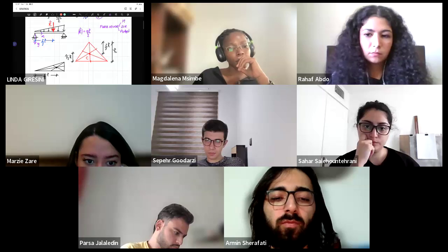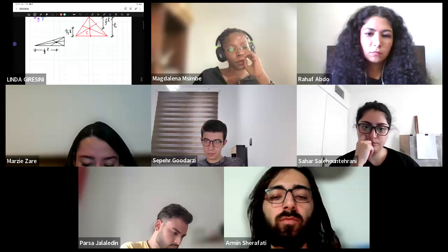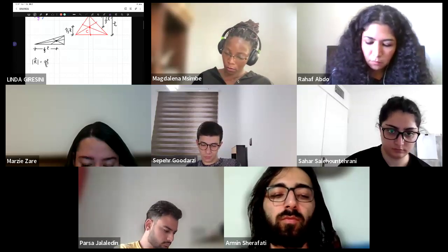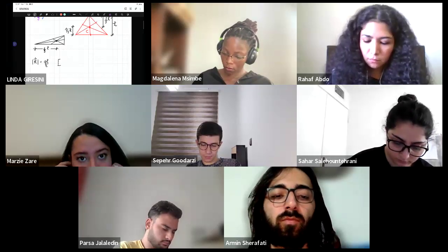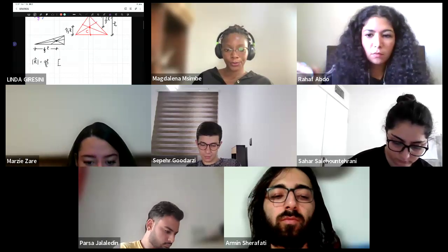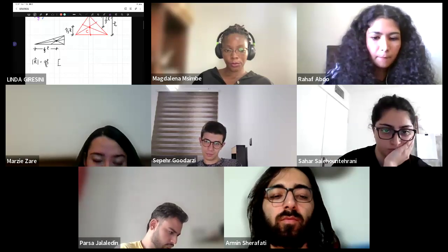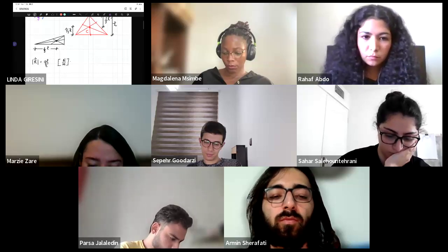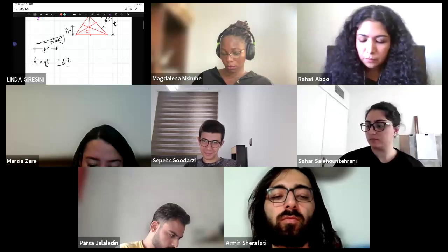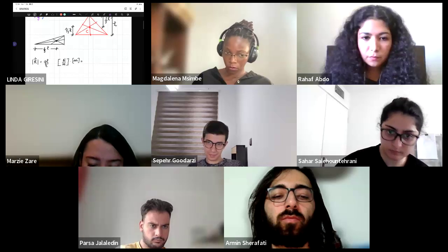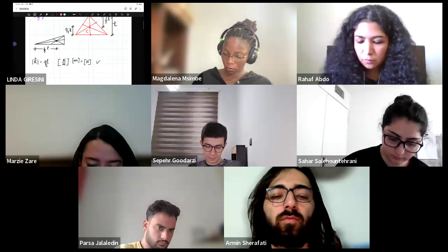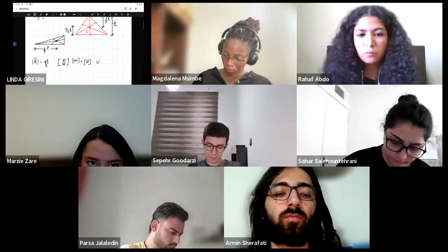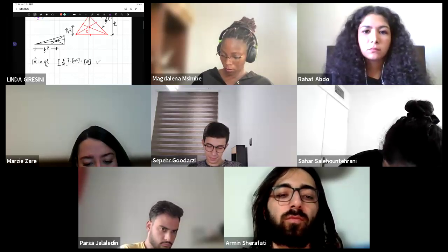Let's check the dimensions, which is always really important. So the resultant is QL divided by 2. So Q, what unit is Q? For example, in newtons divided by meters. So newtons divided by meters times L in meters, and the 2 is dimensionless, of course. So the result is newtons. Correct, because R is a concentrated force, and therefore its unit is a newton or kilonewton, a force in any case.